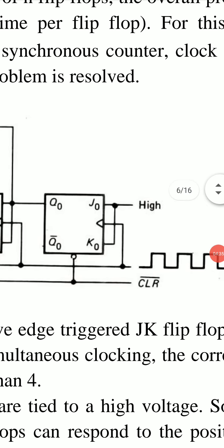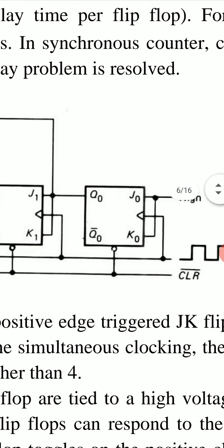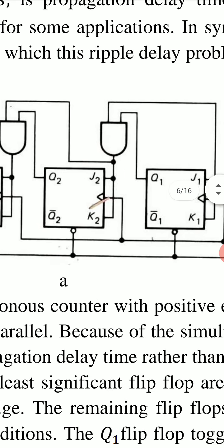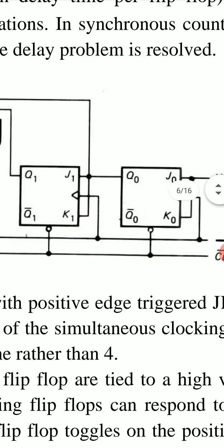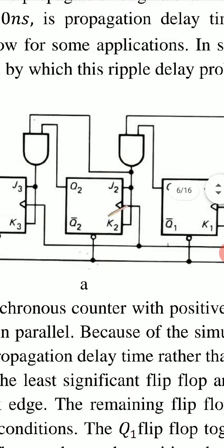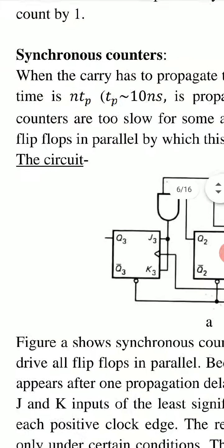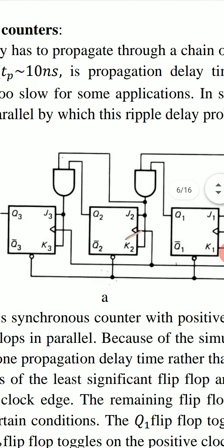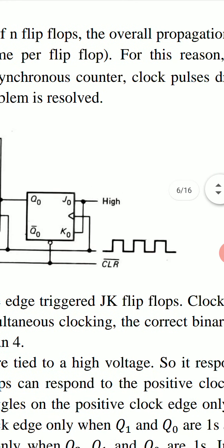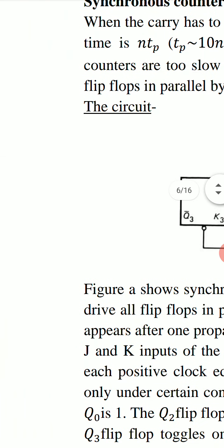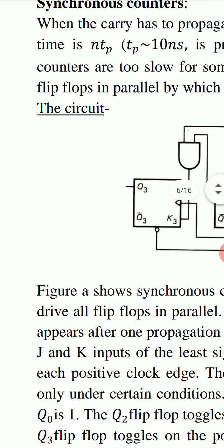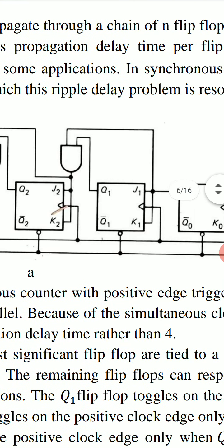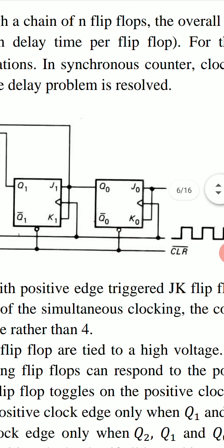In synchronous counter, clock pulses drive all flip-flops in parallel, and in this way the ripple delay problem is resolved.